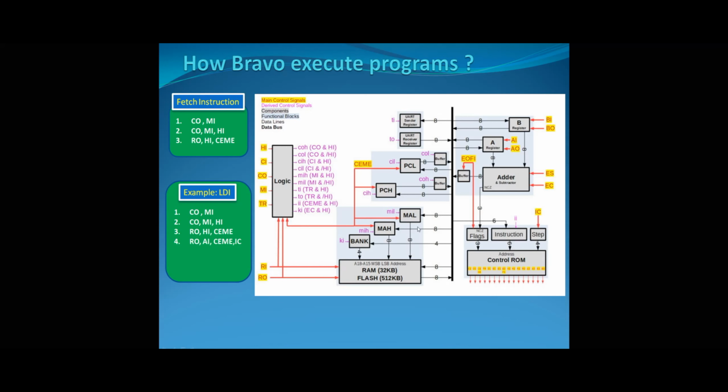Now, on the memory address register, again, on the input side of that circuit, we needed to signal write. Memory in high is responsible for taking the content of the bus and putting it on the high byte of the memory address register, and memory in low is responsible for the same thing, however, for the low byte of the memory address register.